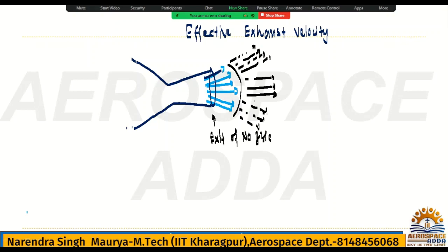Whatever propelling force you get is exactly opposite to this thrust. Yes or no? Exit velocity times flow rate gives the momentum, and the change of momentum gives the force. So whatever the force at the exit, just opposite to it you get the propelling force, and because of that propelling force the system will move in the forward direction. That is a very common thing.